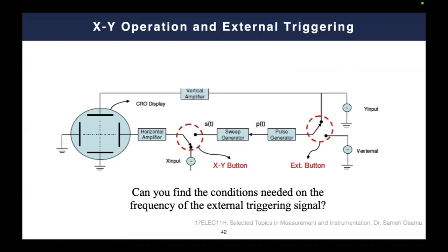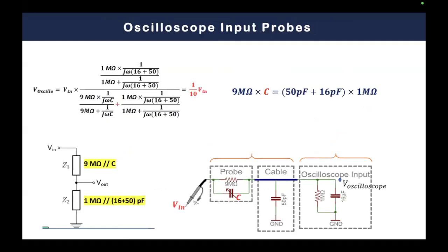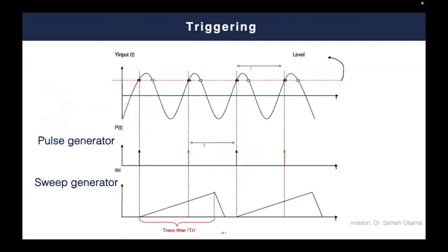The second point to mention in this third part of the lecture is what we call the XY mode. In the previous part of our chapter, we were only concerned with what we can call a time-dependent representation. So usually we insert a triggering signal in the X variation, or what we call the horizontal variation, in order to ensure a scanning of the point from the extreme left to the extreme right. And our input signal to be sketched, to be represented on the oscilloscope, is inserted on the vertical variation, for example, this sinusoidal signal.